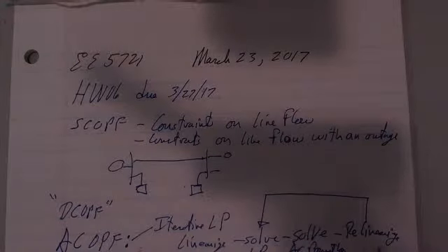You relinearize, you solve the LP, and when you get to a solution, you solve the AC power flow and relinearize until you cease to make any headway. That's a common optimization tool.